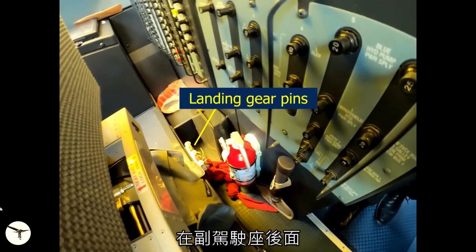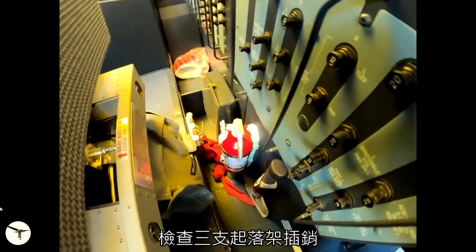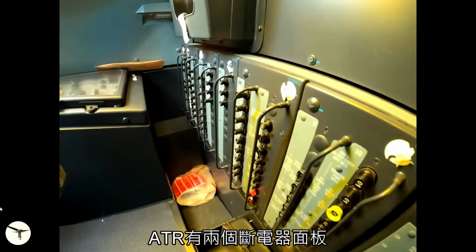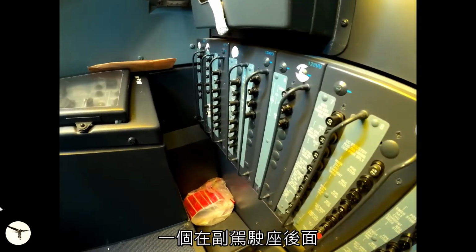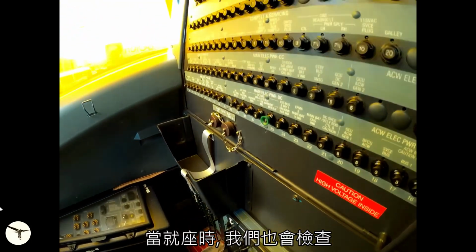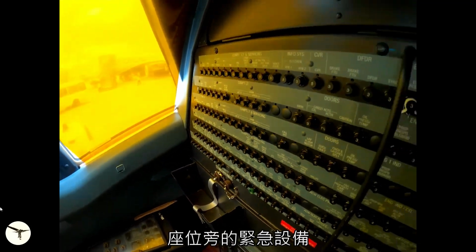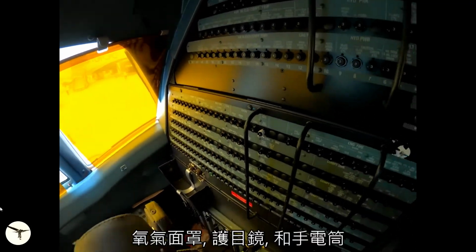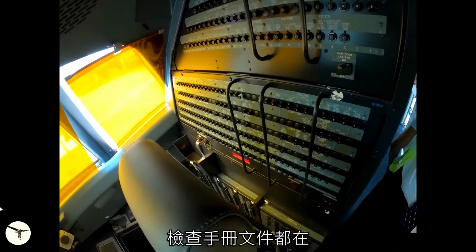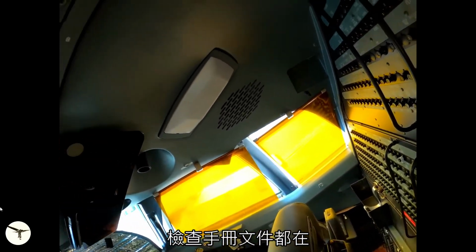We check that the 3 landing gear pins are in place behind the first officer's seat. We also check that all circuit breakers are in. The ATR has 2 circuit breaker panels, one behind the first officer and one in the ceiling. When seated, we will also check the emergency equipment at the station: oxygen mask, goggles, and flashlight. And we check that all manuals and documents are in place.